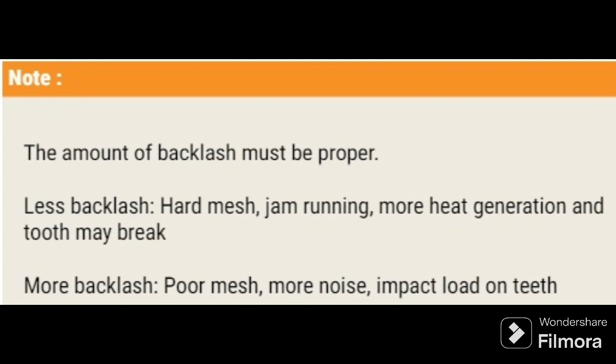Note, the amount of backlash must be proper. Less backlash has hard mesh, jam running, more heat generation and tooth may break. More backlash has poor mesh, more noise, impact load on teeth.